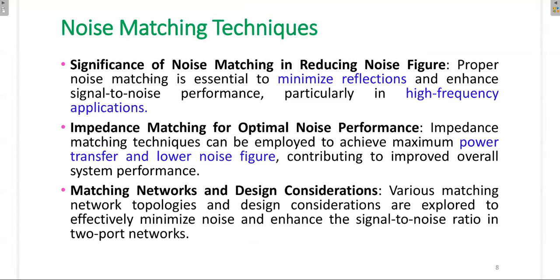Noise matching technique. Significance of noise matching in reducing the noise figure. Proper noise matching is essential to minimize reflections. We know that whenever we operate at high frequency, we have to consider not only the forward waves, we also consider the reflection waves. So we have to reduce the reflection waves in order to minimize the effect of noise and enhance the signal to noise performance, particularly in high frequency applications.